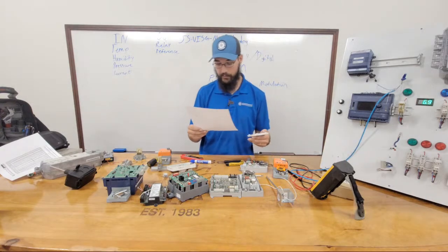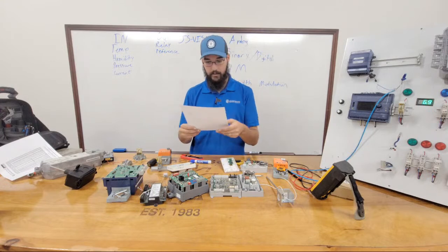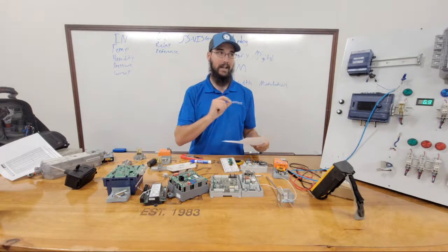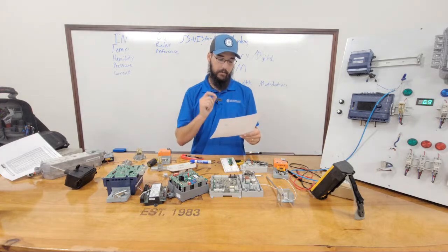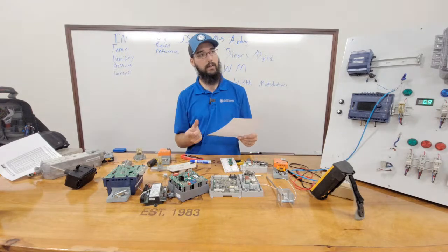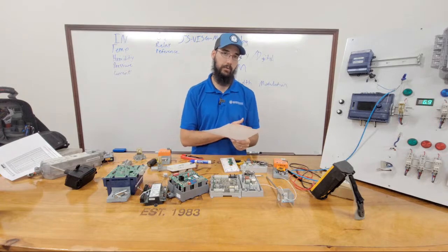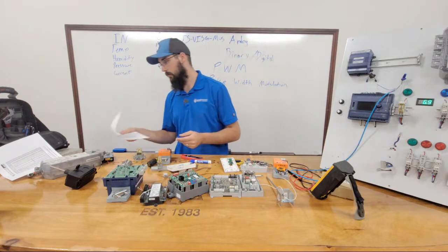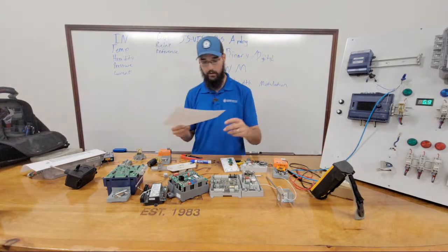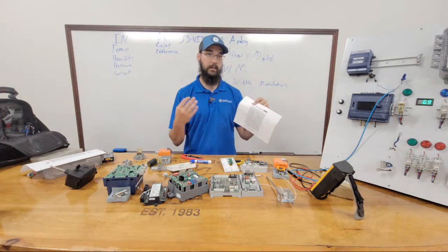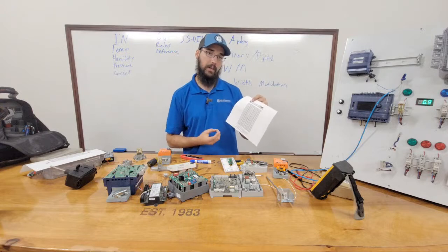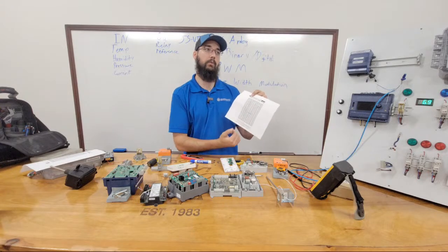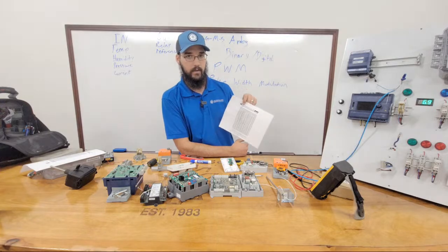So the difference being, a 20K means that at 77 degrees, that thermistor is going to read either 20,000 ohms or 10,000 ohms. And in terms of your 10K type 2, it could be type 1, 2, or 3, and the difference in the 1, 2, and 3 is the range at which the ohms change.